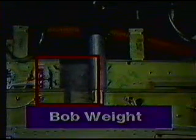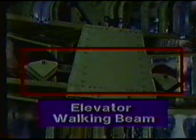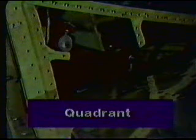The large lead weight connected to the control column is called the bob weight. The large spring installed under the dorsal fairing is called the elevator downspring. The pivoting unit located below the cockpit floor area is called the elevator walking beam. The major cast assembly used to link the elevators and the elevator control cable system is called the elevator bell crank, elevator quadrant, or simply the quadrant.